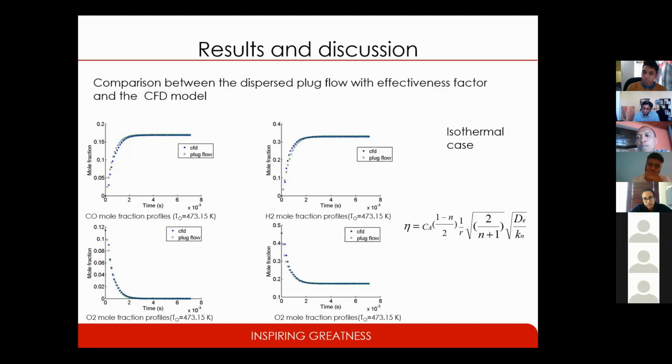Upon combining those 2, I employed the linear combination, with the beta, which is the ratio of the free flow to the zero flow. Then I took that answer and embedded it into, remember I spoke about a single channel monolith? A single channel monolith does not take into account the interaction between the channels through heat transfer.